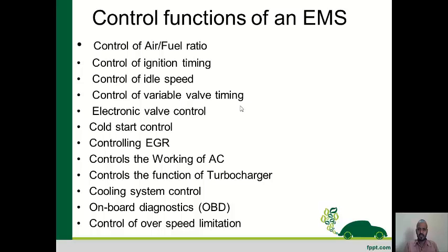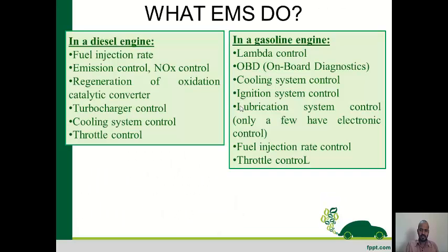Depending upon this, it will control the air fuel ratio, ignition timing, idle speed, variable valve timing, valve controls, cold start control, control of EGR, and working of the AC, because the AC is attached to the engine. Switching the AC on and off puts more load on the engine, so at that time more air fuel mixture has to be provided, and that will be controlled. Also turbocharger, cooling system, onboard diagnostics, and control of overspeed limitations. These are all certain control functions of an EMS.